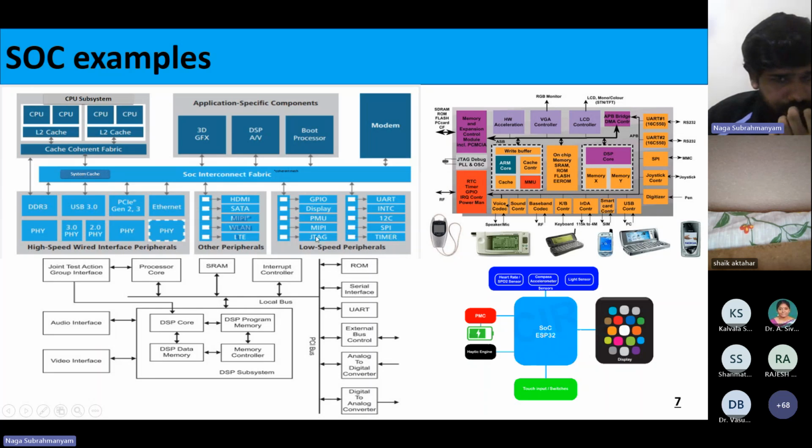These are the various low speed peripherals like GPIO, UART, I2C, SPI. Okay, power management unit. Tomorrow's session I'll tell you how the power management unit will work. And this is another way of representing the SOC. See here, this interconnect is nothing but a kind of fabric. The way we want, the interconnect will change the circuit and it will route the data. Suppose the CPU wants to access one of the peripherals in this low speed.